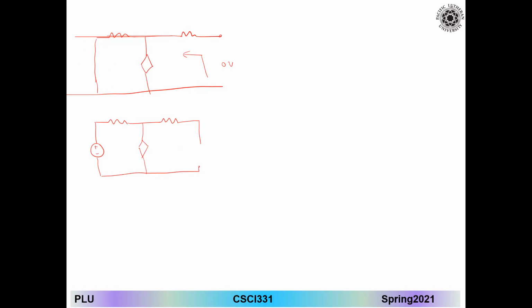Okay, guys, here's the thing. I told you when we have a dependent source in my circuit, I have to stop and think before I just memorize the steps. Here's the R Thevenin. We cannot delete the dependent source. So R Thevenin should be found by V open circuit divided by I short circuit.